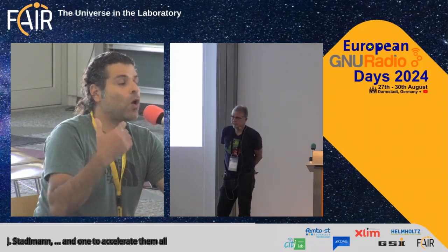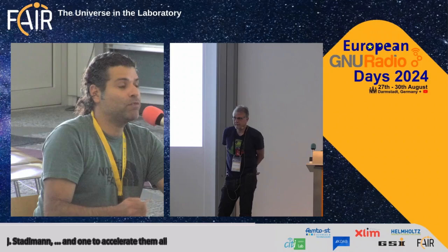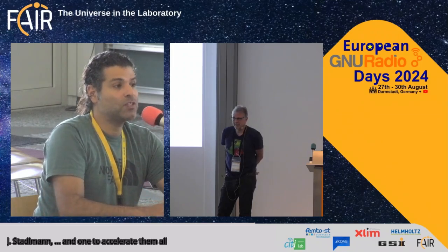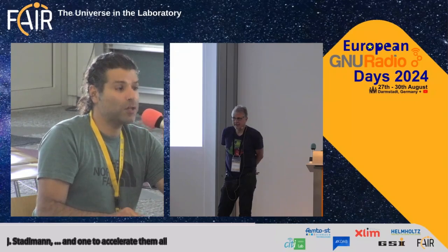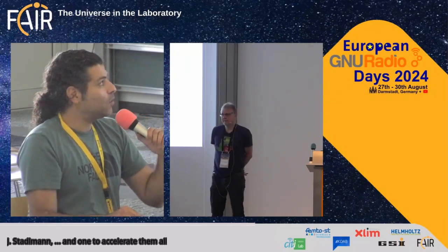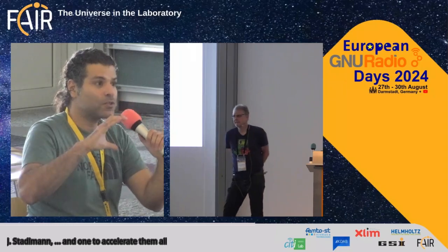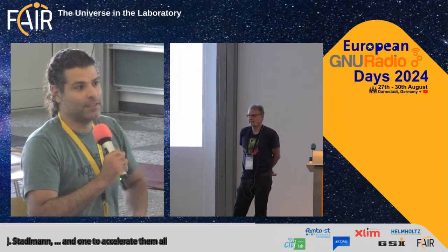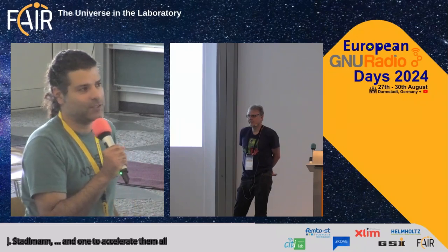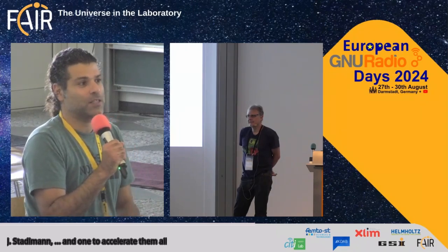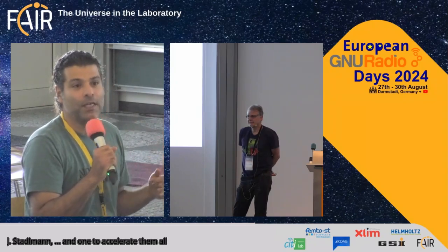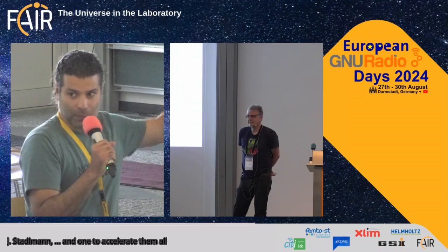So there's a huge amount of different information that you can get from these RF detectors, because they are non-destructive. That means they are really just kind of antennas around it. I really hate the name antennas, because they are not really antennas. You can consider them as a secondary loop of a transformer whose primary loop is the particle beam itself.